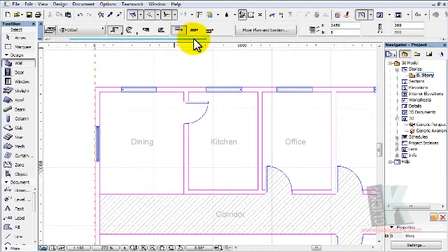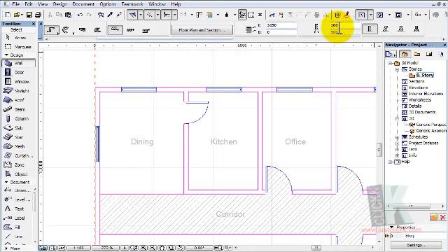Okay, so let's slide this. You have a slider here that is simply telling you there are more options on the inside. So by the time you slide, you will see more options. This is the thickness of the wall. What do you want the wall to be? Is it 225 or 900? I mean 150. So if it is 9 inches block, then you put 225 here and press the enter key. But if it is at 150, I mean 6 inches block, then you should put 150.